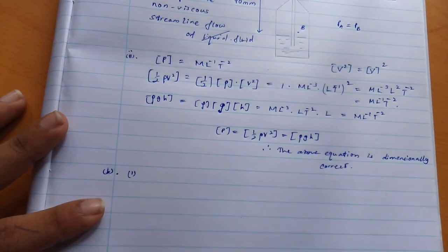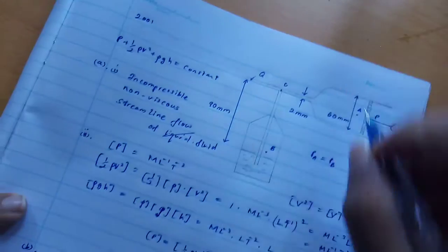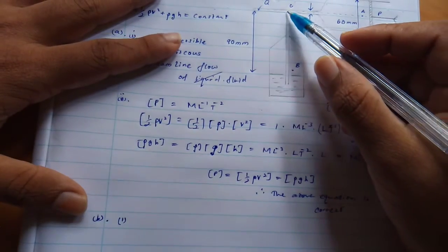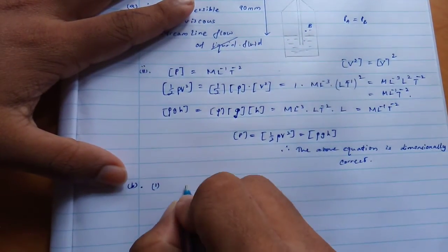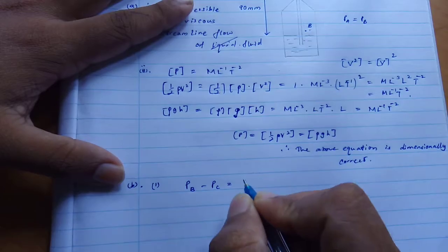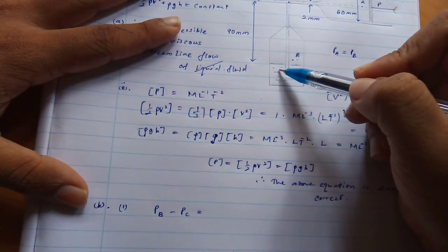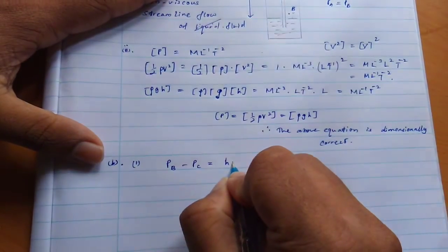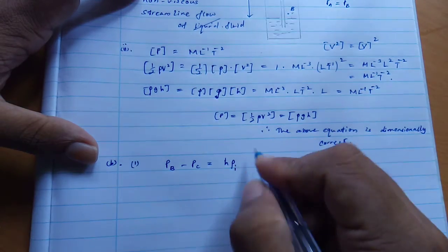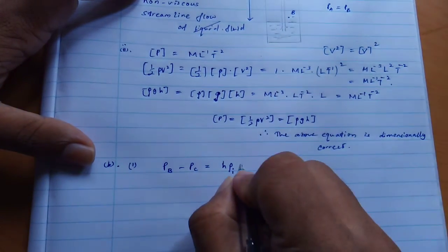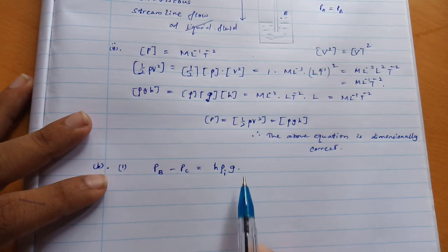For that, first I had to consider that the liquid has to be raised up to this point. Now I consider this point as C. Therefore, if the liquid rises up to this point, the pressure difference between these two points, PB minus PC, should equal the pressure difference due to the insecticide rising in this air column, which is H rho. I take rho here as rho I, the density of the insecticide, times g. So the pressure difference has to be H rho I g. Okay, so this is one equation.